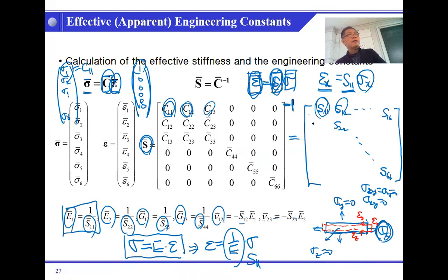And put it here. How to get the stiffness? Well, numerically, we invert the matrix. Okay, actually, this is what we covered last week. Simply a 6x6 matrix and all the material properties. And these are E1, E2, and G12 and G23.